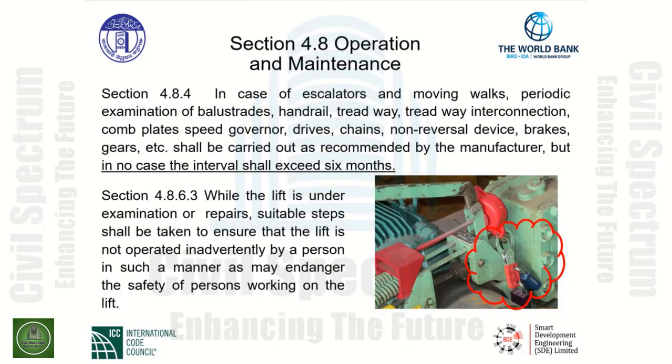Section 4.8.4. In case of escalators and moving walks, periodic examination of balustrades, handrail, treadway, treadway interconnection, comb plate, speed governor, drives, chains, non-reversal device, brakes, gears, etc., shall be carried out as recommended by the manufacturer.